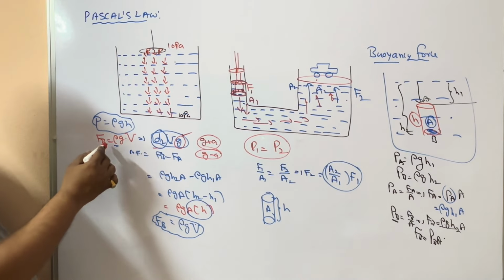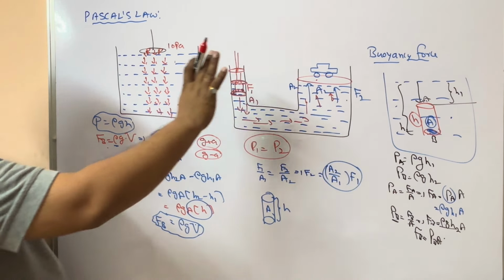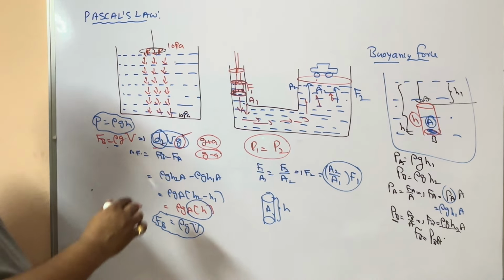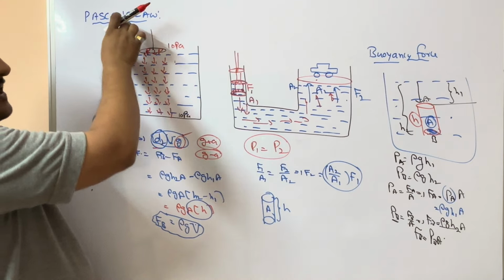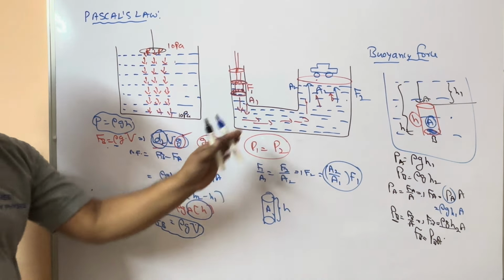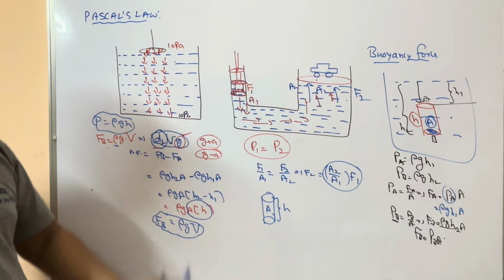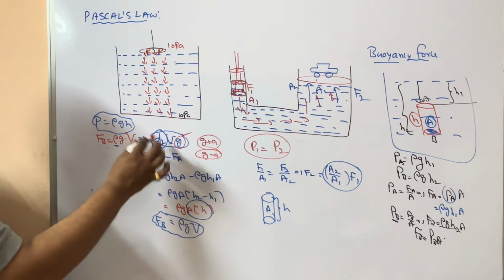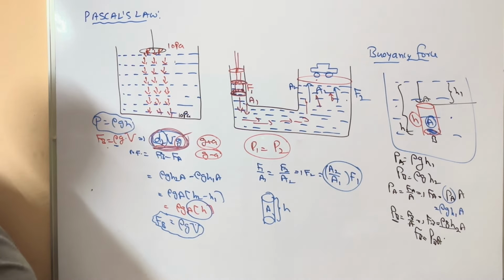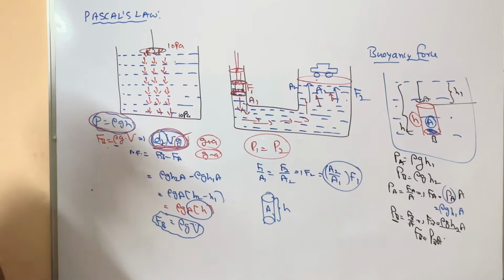So now, buoyancy force depends on the density of the liquid. It will not depend on the mass of the body. So in this, you got two points: one is Pascal's law, another is the buoyancy force equation. From here, next we will get Archimedes principle and so on. We will discuss that in our next class, but be ready for this equation. You will use this equation many times, like how you use pressure, rho g h, now buoyancy force, d_l V g.